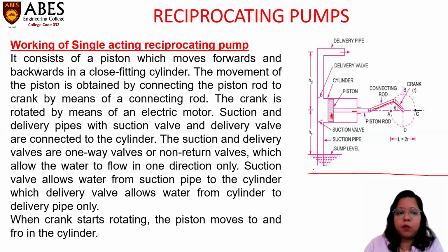Suction and delivery pipes with suction valve and delivery valve are connected to the cylinders. The suction and delivery valves are one-way valves. These non-return valves are attached in the suction pipe and delivery pipe. This is the delivery pipe and this is the suction pipe. The suction valve allows water from the suction pipe to the cylinder, while the delivery valve allows water from the cylinder to the delivery pipe